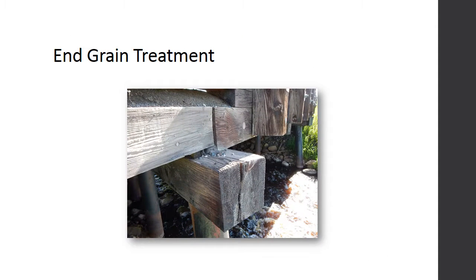Without preventative measures, the ends of timber members are more susceptible to drawing in water than other portions of the member. If the end has been cut, a timber treatment should be brushed on, and where exposed, should be capped with flashing such as tin, aluminum, or similar material, with minimization of water exposure being the goal.